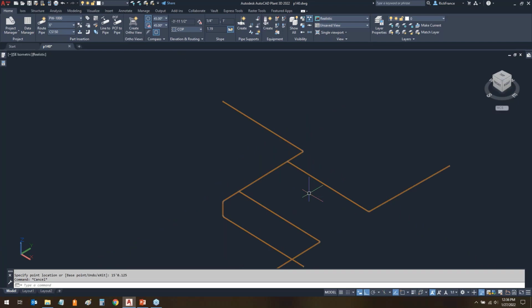The reason I say it's the least accurate, that 15 1/8, you think about AutoCAD rounding, it's rounding to the nearest 1/8 or 16th or something like that. I think this one's rounding to the nearest 1/8 in this particular drawing because that's what the units are set for. If that's the case, 15 1/16 would round to an eighth. 15 3/16 could round up or down, depending on where it is, to an eighth.